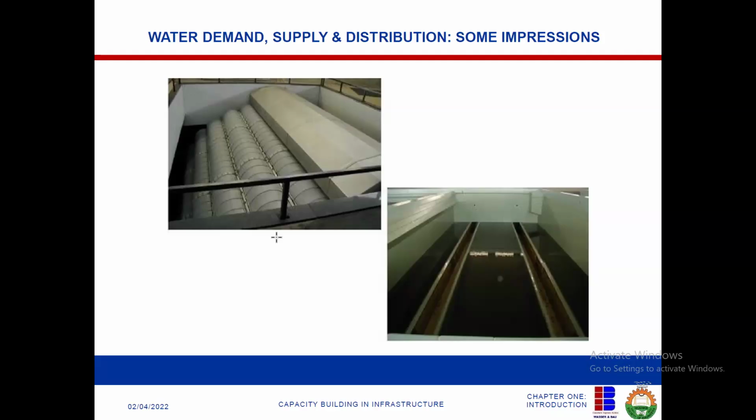So basically, they come in the form of iron 2. When you aerate them, they move from iron 2 to iron 3, 2 plus to 3 plus. Iron 2 is normally soluble in water, but iron 3 is insoluble in water, or partially soluble. So when you aerate water, the first thing that happens is that iron 2 gets oxygen and converts to iron 3.